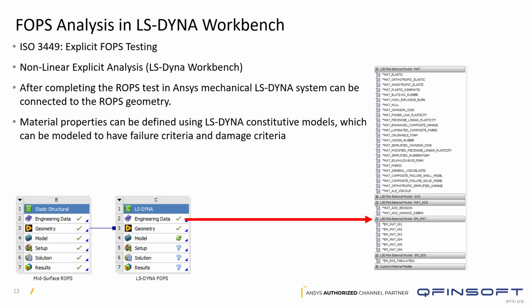And then from there, inside of the engineering data, we can go a bit into more details. We have more material models that we can look at inside of LS-Dyna, depending on the material that we have and the kind of testing that we're doing. We can go and simulate stuff like if the impactor actually breaks the structure, we can set a criteria for when it breaks, and then we can insert some kind of breakage model inside of this test.